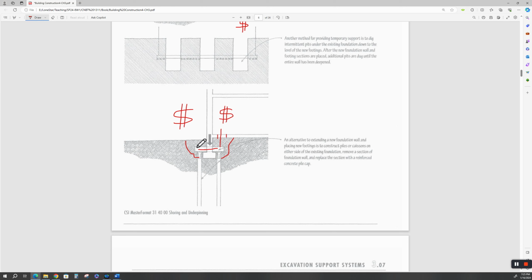Now, the big question is, and some of y'all have probably already thought about it, well, compacting all this dirt back in here is one thing. How in the name of Zeus do you get underneath an existing slab and compact this? Well, irrespective of what these contractors tell you, you really can't. You can crawl these little guys back in there with pneumatic rams and try to compact all this stuff as best you can, but you'll never get it as compacted as it was in the beginning. The best thing to do is to avoid this with good upfront foundation engineering.